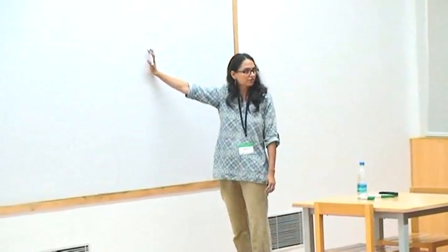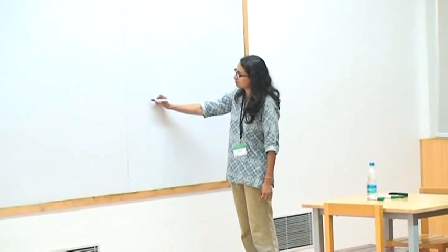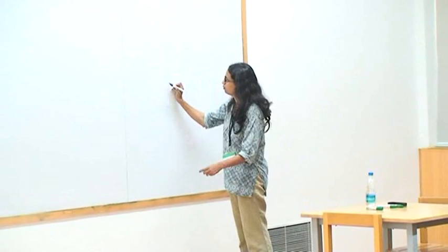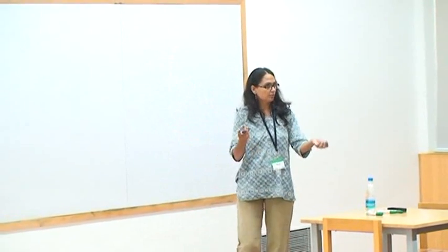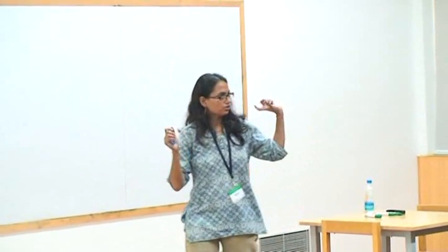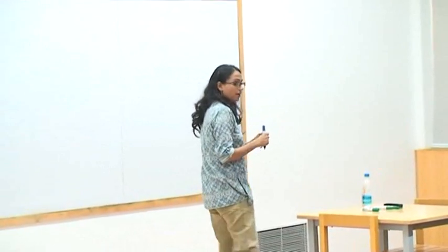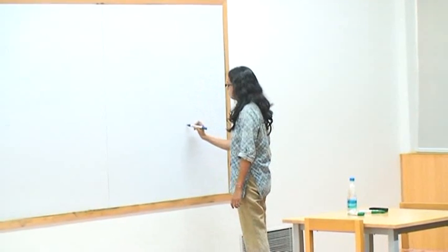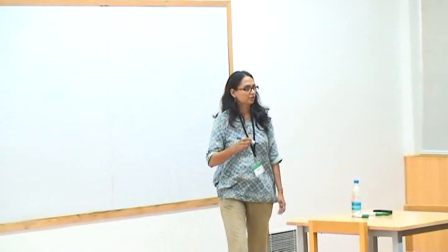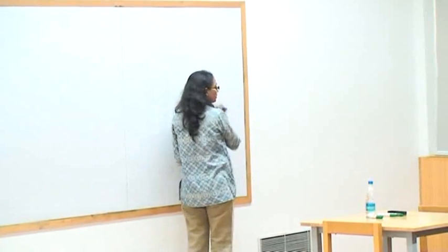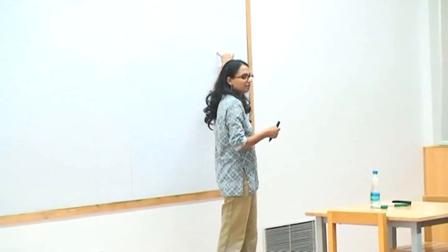So if you have a rectangular piece of PDMS and you are stretching it, of course it doesn't stretch uniformly like this. It would stretch like this, so you have a contraction in this direction and an extension there. How much of this contracts depends on the material properties and the Poisson ratio. Now, something we are doing in the lab to exploit this: if you stretch it, the points here will get more easily stretched than points there, because it has support.